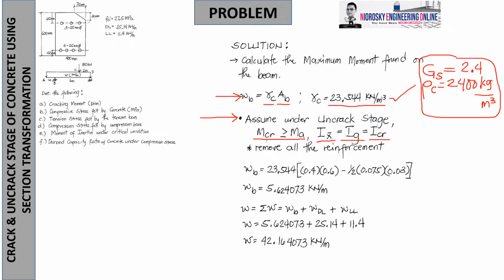Now, again, I have removed all the reinforcement. Our code says that to calculate the cracking moment, there is a requirement to assess I sub g and y sub t neglecting reinforcement. Meaning, we are to remove the n minus 1 times As that we discussed, if you recall, under tension. By the code, we neglect the reinforcement under tension.